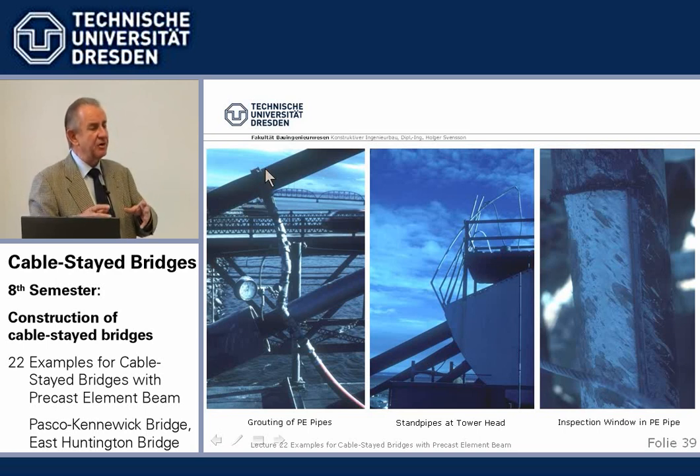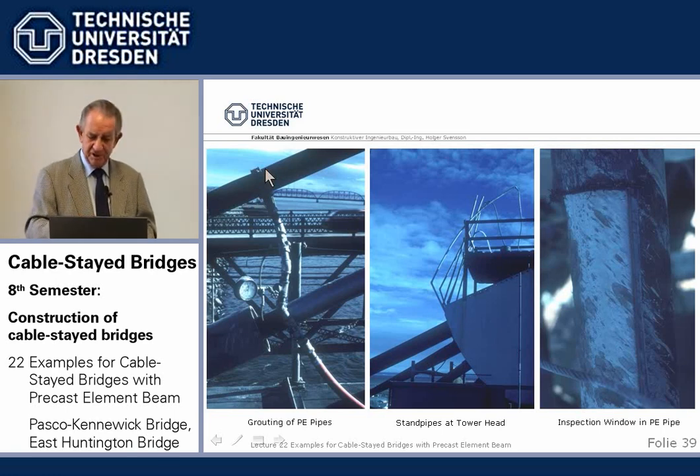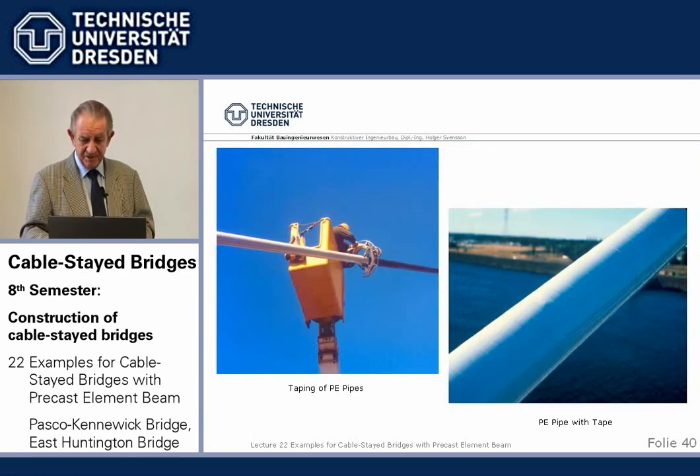And then, of course, the cement hardens, and the strain is frozen in. And then after 2-3 years, the PE pipes crack. It's a long story. I just want to say there are some shortcomings with this cement grouting. It works beautifully, but tedious. So we used later the petroleum wax. Finally, the coloring.